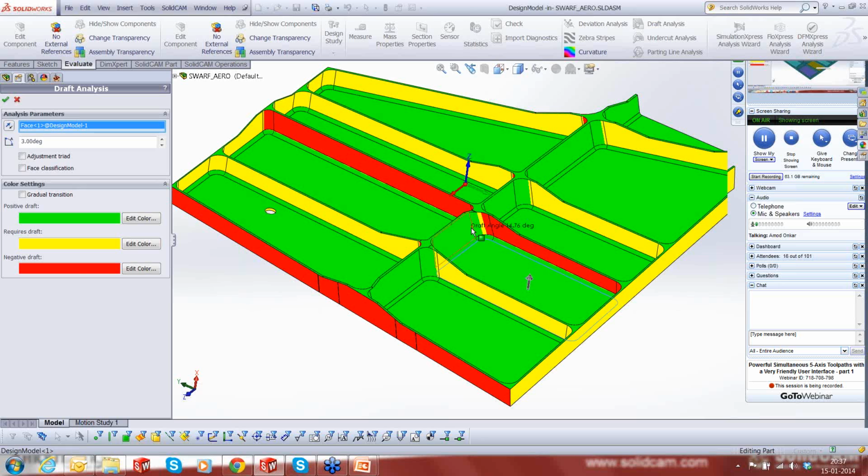We would like to cut this, because in the aerospace industry, if these walls have to be cut, they will be cut using a 3D function on a 3-axis machine. If I have to take this on a 3-axis machine and cut, I'll have to put several passes to finish this. Whereas in 5-axis, I could use just the side of the tool and cut exactly this surface in just one pass, depending on how much material there is. I could go one pass, or I could go in 3 or 4 passes. I could just finish this off.